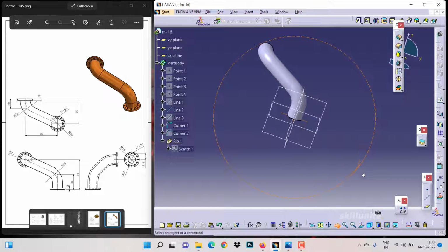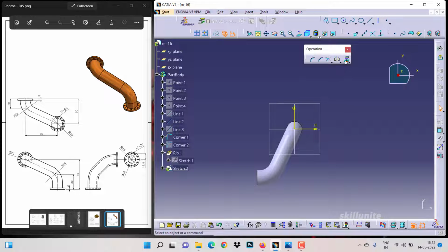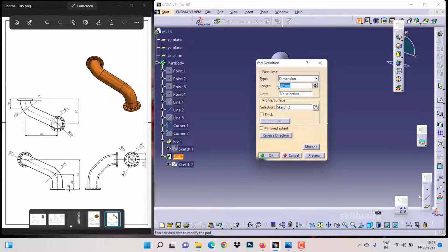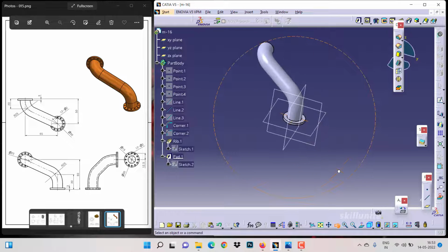So now what we have to do is create the base and the top we are having. That is simple. Extrude option, that is the pad option, we are going to use over here. So let me use the project option. Let me project this one, and the outer one, as you know, is diameter 30. Let me create that. And the cutouts whatever we are having, maybe we will do them in 3D, so that we can easily make a pattern of it. So now go for pad, and 3 mm is the thickness, and reverse direction, and then click OK.